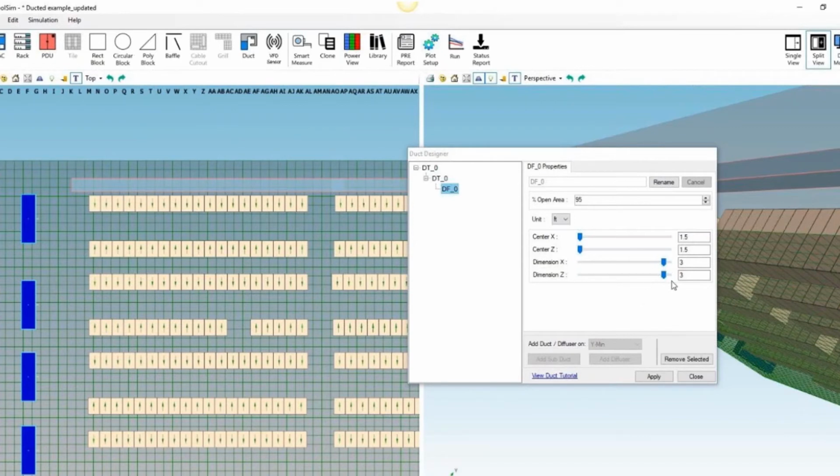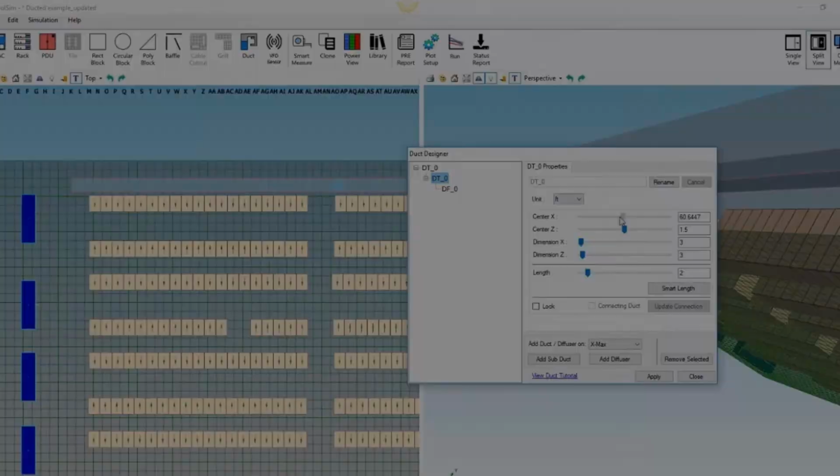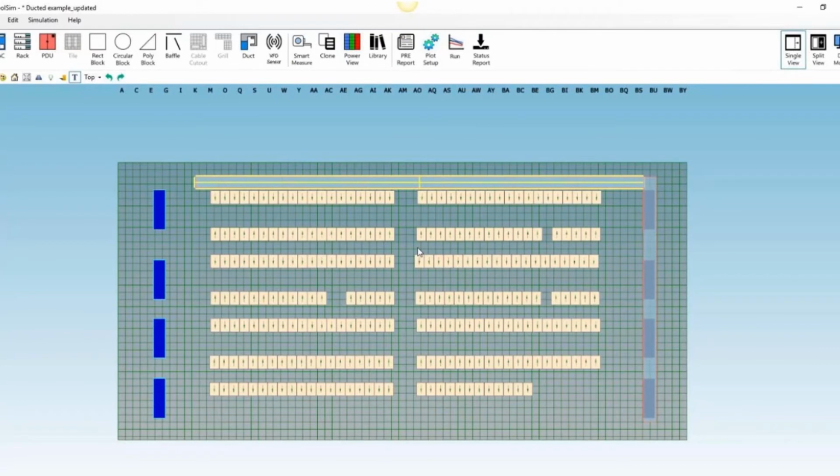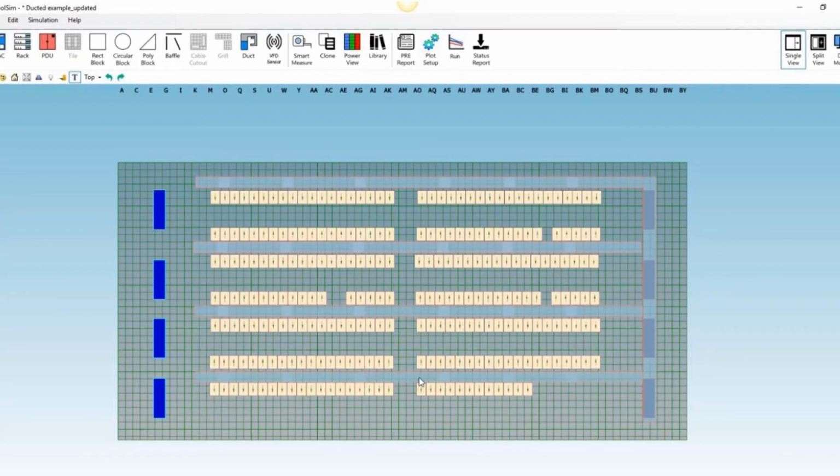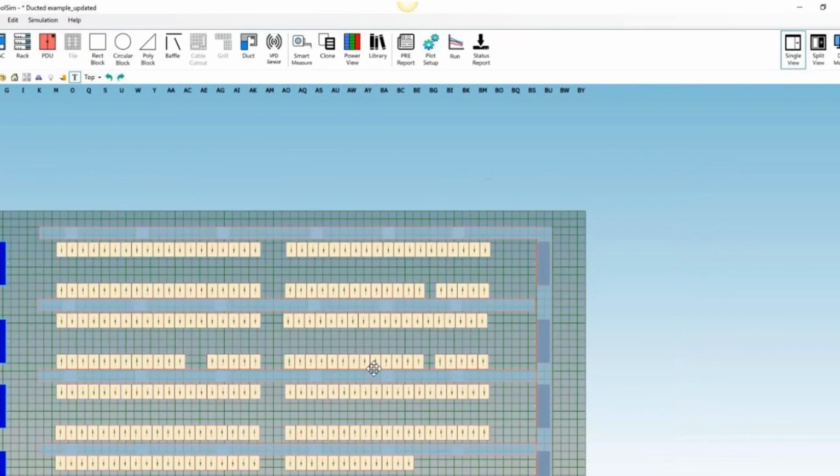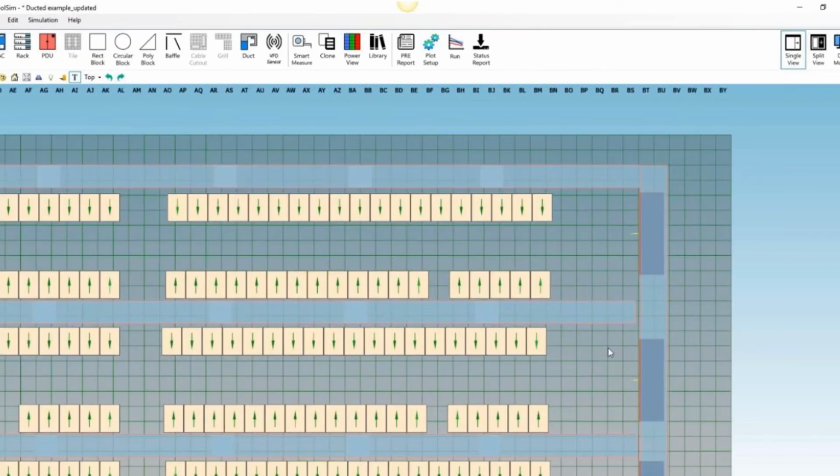So there's my sizes there, and I go ahead and make those subducts like I did before. There's N of them to make, and for purposes of illustration, I did those for you offline. And now what I'm doing is I Control-C'd it, and I'm Control-V'ing the entire subduct into position. Very nice. I can take the whole thing and just Control-V it. Control-C, Control-V. I could also clone it. If the offset was the same, I could have done a clone of 3 with a common offset.